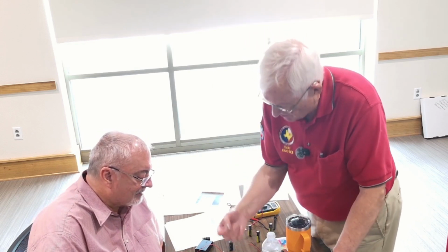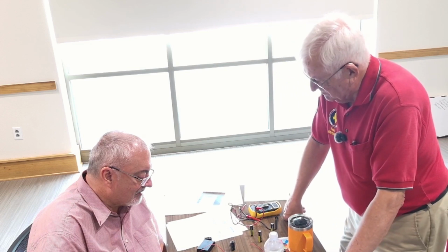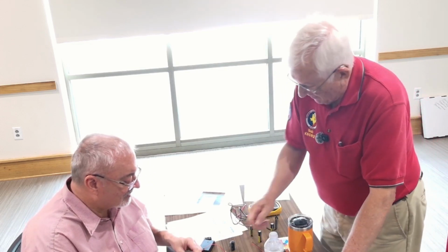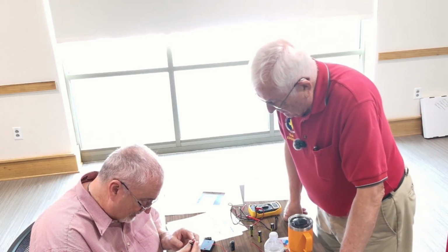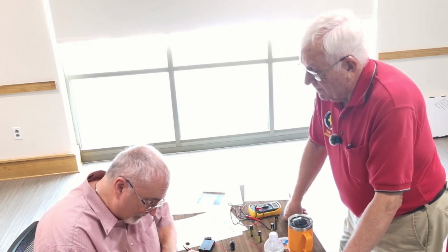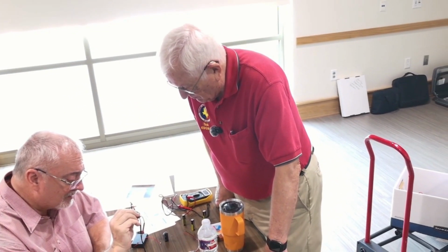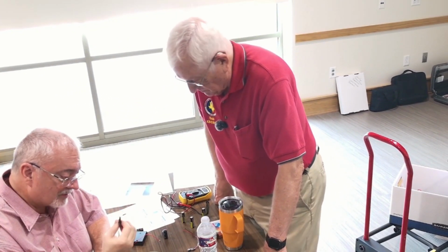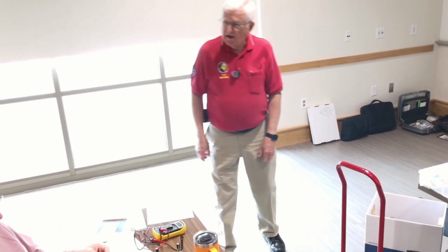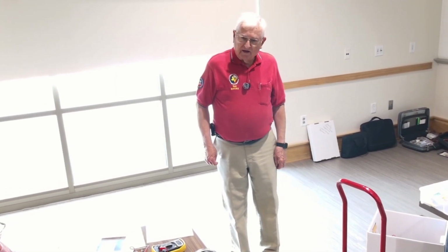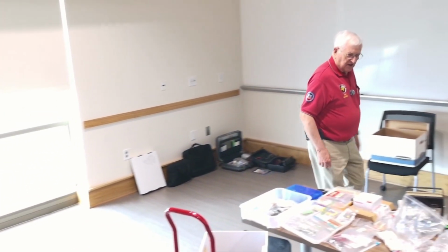Like I said, the tolerances on these things are way wide. They're usually like plus or minus 25%. Then when you get to the picofarad one, though, then you can start getting into some real close tolerances if you want to do that. 3.18 nanofarad. Now this has 0.004 microfarads, which is 3.18 nanofarad. Yep. That's neat. Okay. What do we think, gang? Everybody get a chance to play a little bit? And you'll probably notice if you try to read those numbers on those things, it can be a little bit crazy, to say the least.